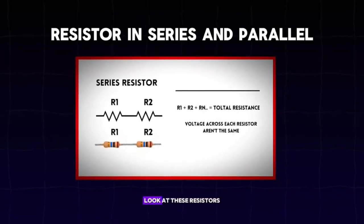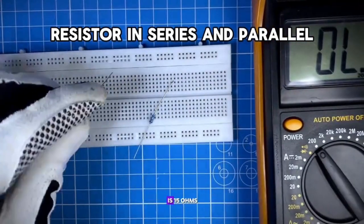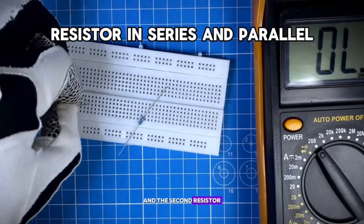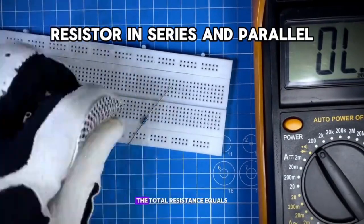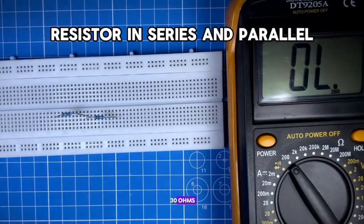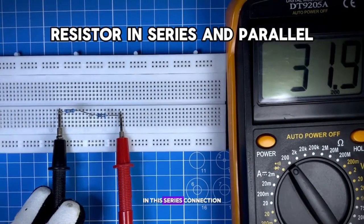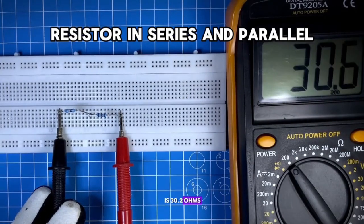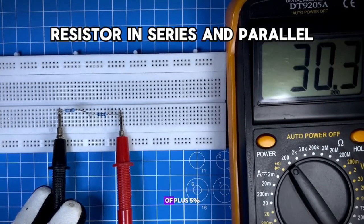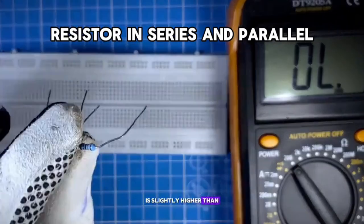So practically look at these resistors. The two resistors are connected in series. Since the first resistor is 15 ohms and the second resistor is also 15 ohms, the total resistance equals 15 plus 15, or 30 ohms. As you can see in the multimeter display, it shows that the total ohms of these resistors in this series connection is 30.2 ohms. This indicates a tolerance of plus 5%, as the resistance is slightly higher than the actual